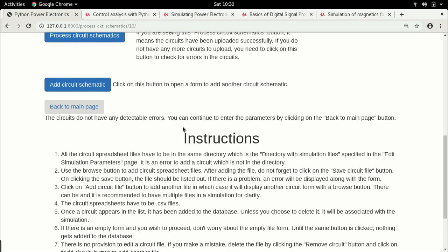So with this, we now have a test circuit for our 3-winding transformer, and with which we can now write our new magnetic model, and we can now adjust this magnetic model to account for the 3rd winding in our transformer. So we can then take this transformer model and place it in a forward converter, which is what we were working on before. So since this lecture is getting pretty long, I'm going to stop this lecture now.